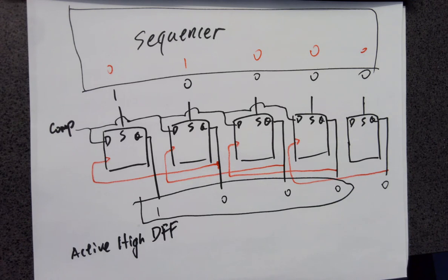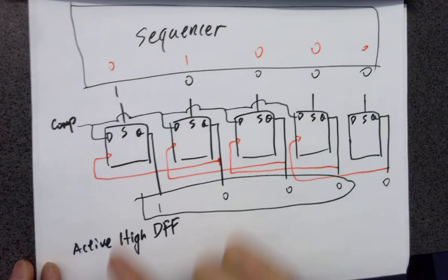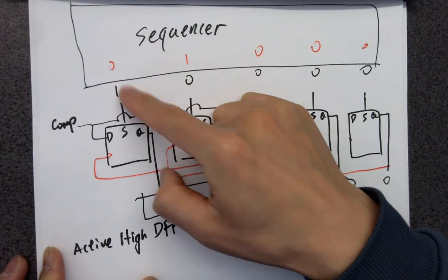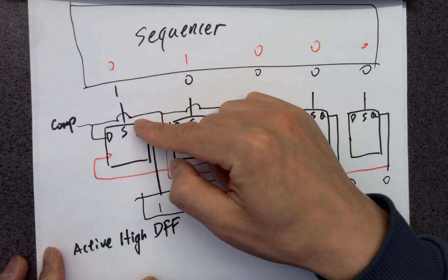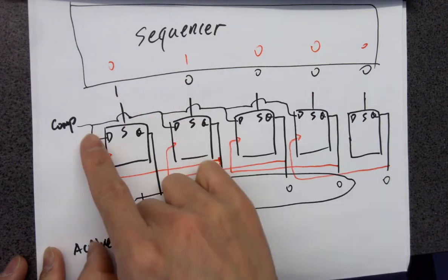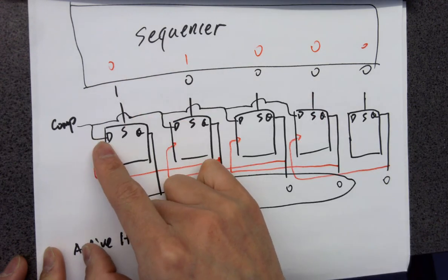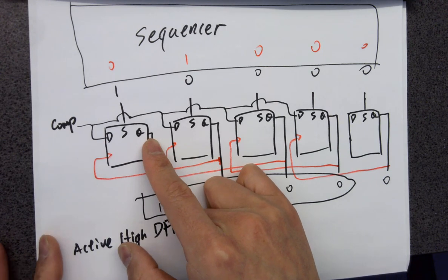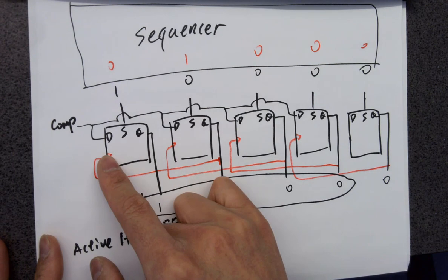Take a look at it. So keep in mind for the D flip-flop, if you set it, it's not functioning properly. So if you set it, you're definitely getting a 1 at Q, right? If you don't set it, which means if you give a 0, because these D flip-flops are active high, which means 1 will set it, but 0 is not doing anything. So if you give a 0 to set, it's operating as a D flip-flop. It's taking D into Q at every clock cycle. And we assume it's rising edge triggered.